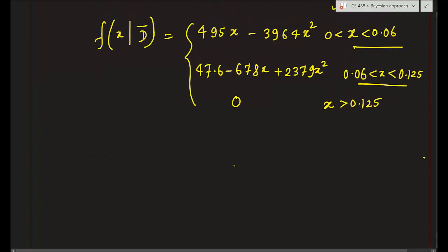So this is what we have in this lecture or in this video. To summarize, the Bayesian method is an important method that can update the information coming from the sensor to achieve a task, whether a given damage has been detected or not. What is the probability that a given length has not been detected? Such questions can be answered using the Bayesian technique by integrating the non-destructive testing data. This is one application of the Bayesian method that is widely used in the engineering industry.